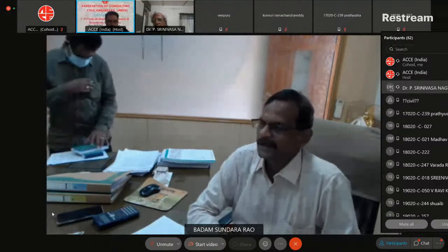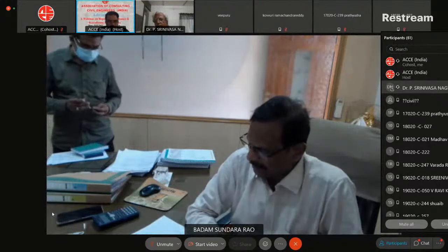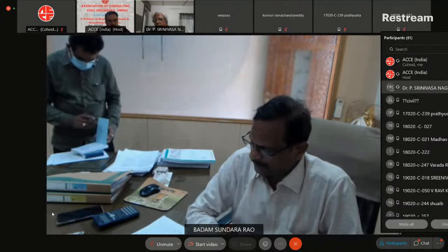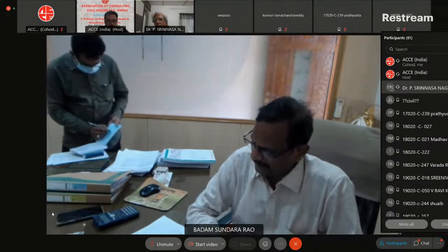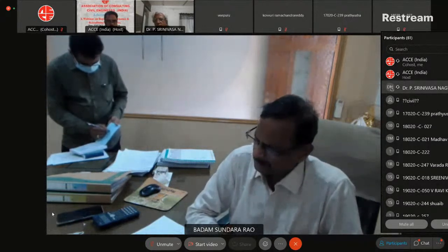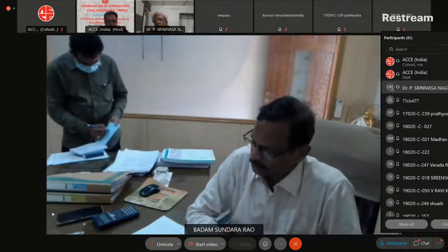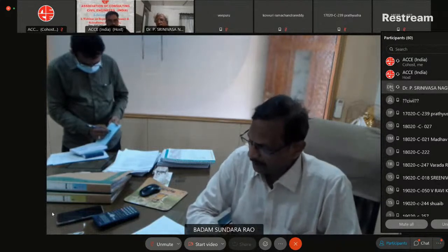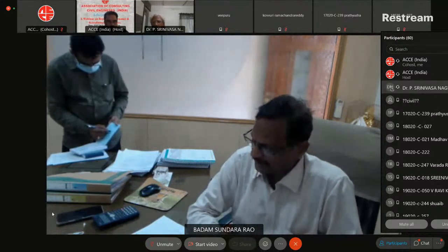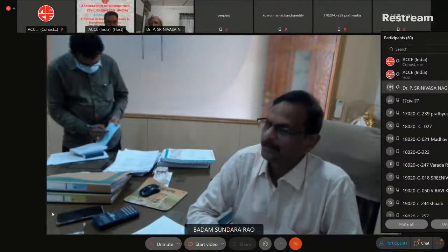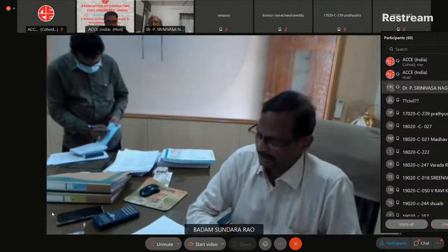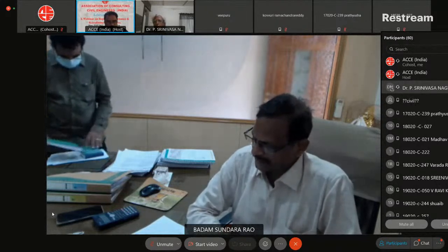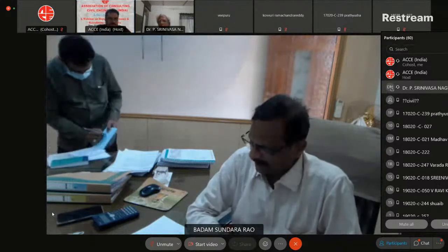Permeability is another important aspect which is to be considered by the engineers while executing the works. As I explained in my webinar on durability of concrete, the permeability depth should not exceed 20 mm. If that exceeds 20 mm, it leads to corrosion. To avoid that, to control the permeability, which is a durability aspect, one should take care of it.